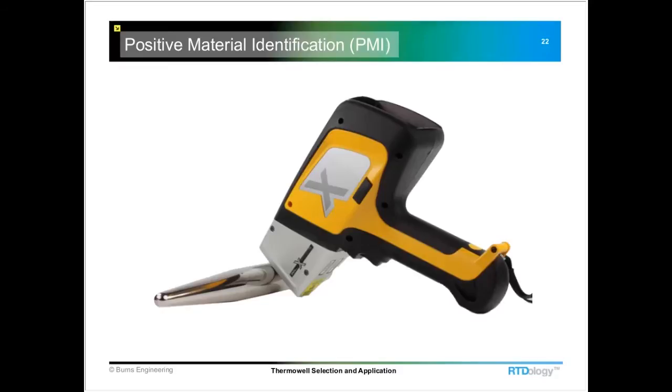And you also want to make sure that if you do specify some exotic alloy Thermowell in a critical application, you want to get the material certification for that, but you may also want to request a positive material identification. This is done with X-ray fluorescence, and it will give the exact composition of that material, just as another check, to make sure that you're getting what you specified and it will be successful in that particular application.